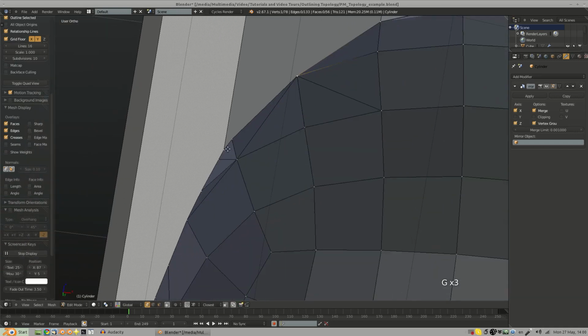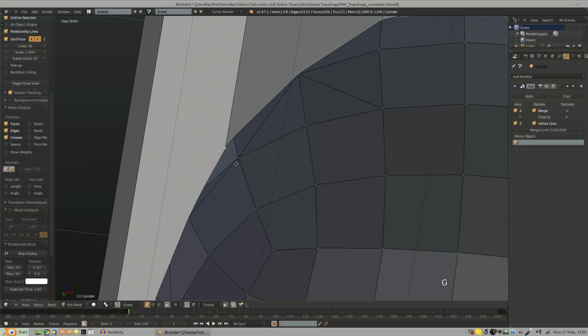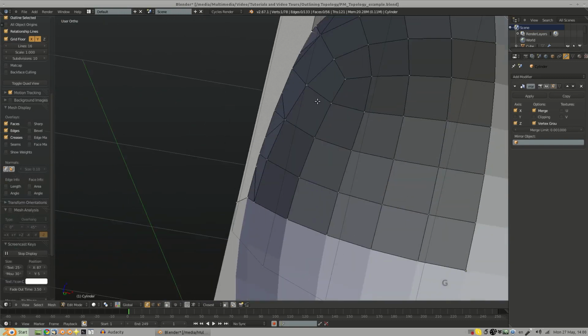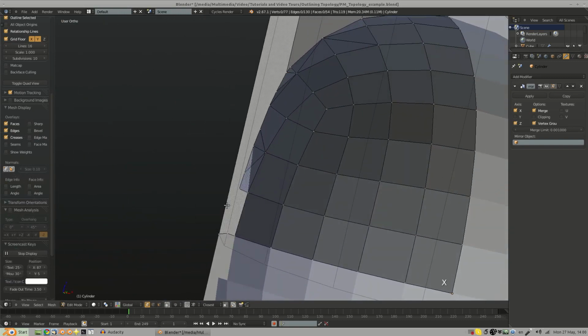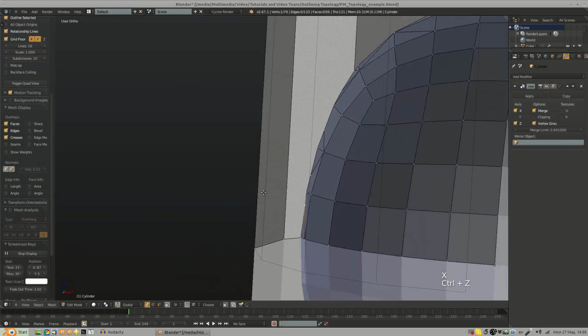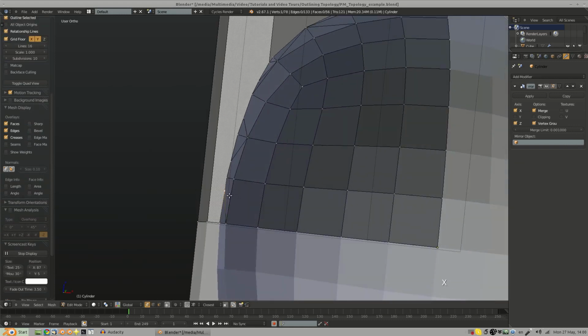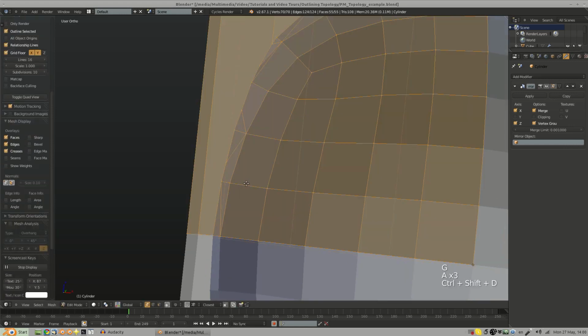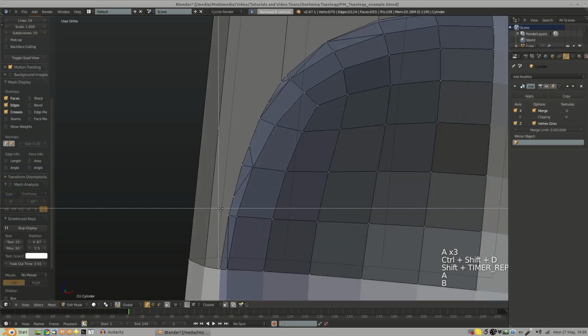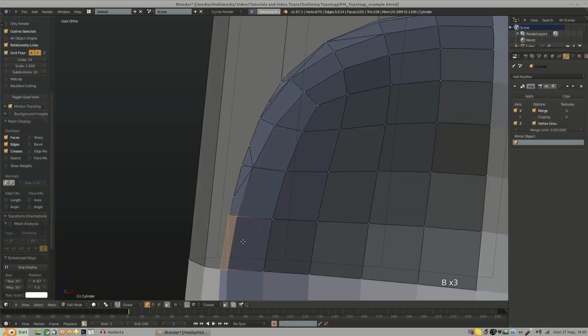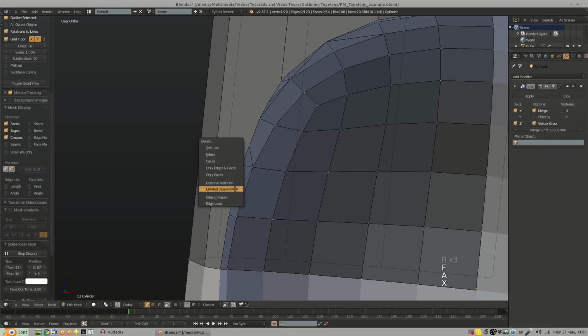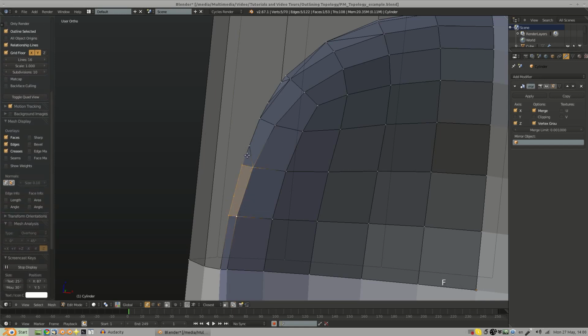And just to, in general, simplify what we're dealing with here, just so we can keep our workspace nice and clean. So this one we don't need. And it's really not working quite well. I don't know what it's doing, but it was not doing this earlier. There we go. So I'll just remove doubles and convert these to quads. And that one we don't need. Wow, it really doesn't want to work. It worked earlier. Yeah, okay, forget it. I'll just fill that in with an n-gon.